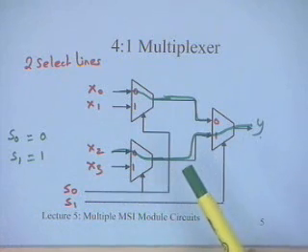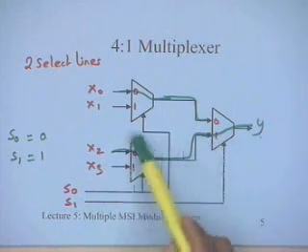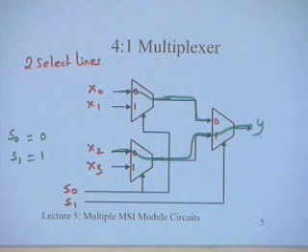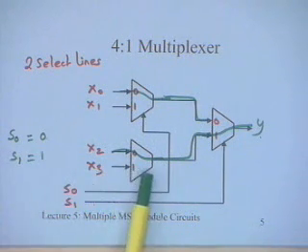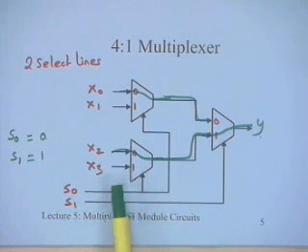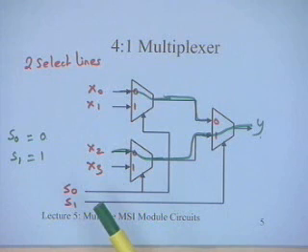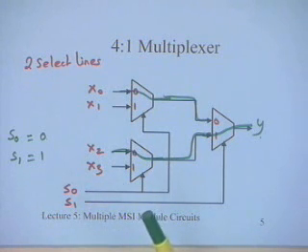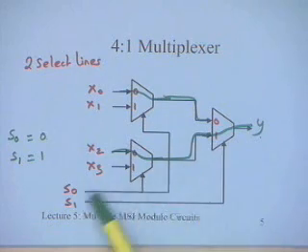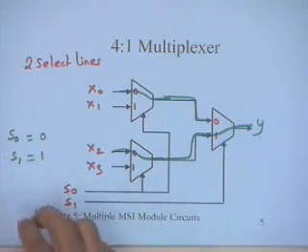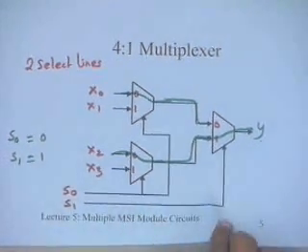The delays are going to add up, and the number of multiplexers that you require is also going to add up. It's fairly simple to construct such multiplexing trees or decoding trees with any larger decoder or multiplexer. You don't have to start from a 2:1 multiplexer, you can also start from a 4:1 multiplexer. Similarly, you can start from a 3:8 decoder. So it's fairly simple to construct such trees depending upon, of course, what you want to implement and what components you have.